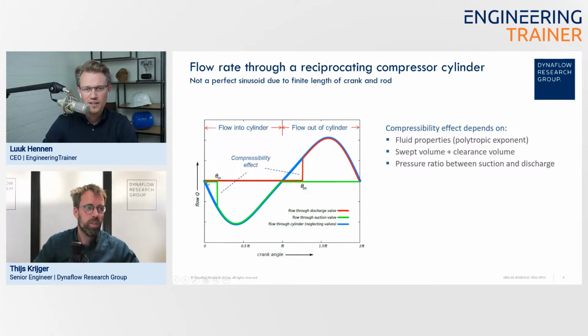Yeah. So it moves a certain distance until the pressure within the chamber reaches the pressure at the suction side. Yeah. And once it becomes lower, this check valve will open, and then you have this sharp step to the movement of the piston, which will be the displaced volume at that pressure. Yeah, that is the check valve opening, that jump there.